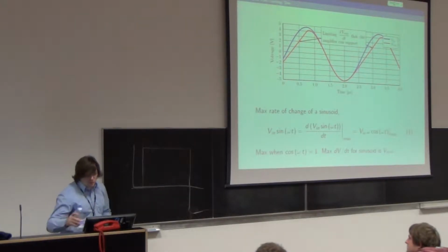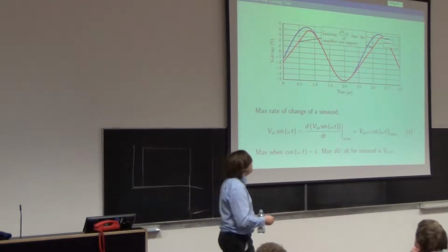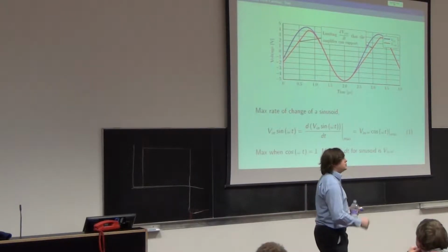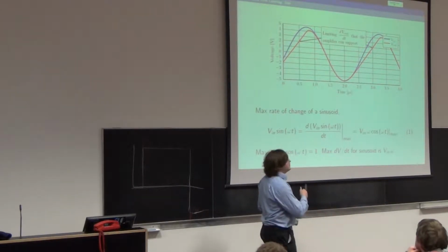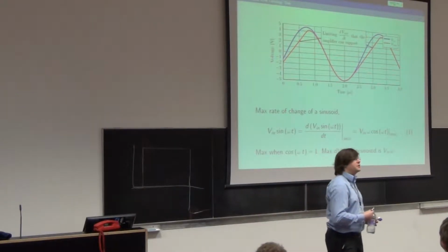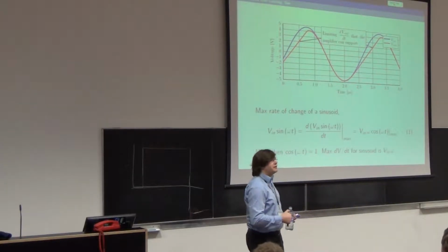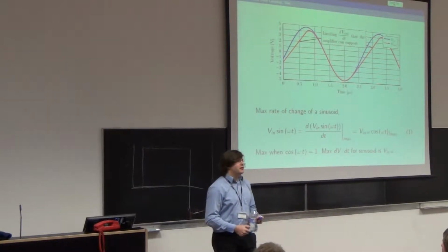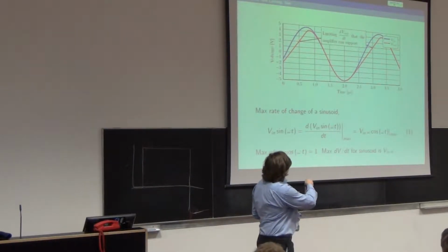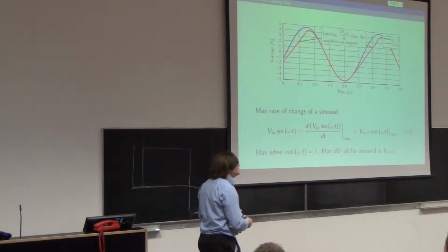So let's have a look at the sine wave. This one really is an op amp, although I also adjusted this one a bit as well. Because if you try and do this in Spice, what you'll find is the phase shift between your input and your output, because you're at quite a high frequency, because that's where slew rate becomes quite apparent. So I've phase shifted them to make them look together, because that's how you see it in a textbook. If you're looking at it in the lab or in Spice, actually you'll see there's essentially a time shift between red and blue, but I want to make it consistent.